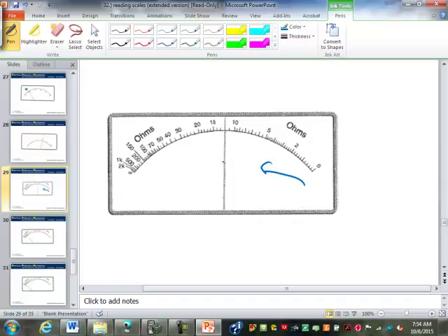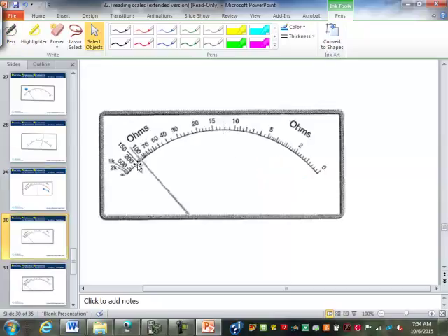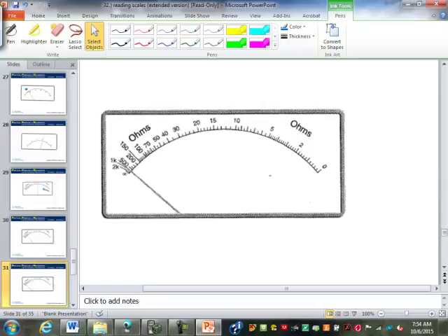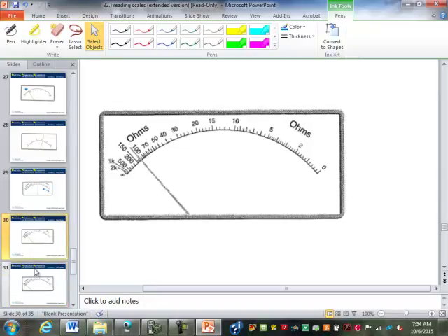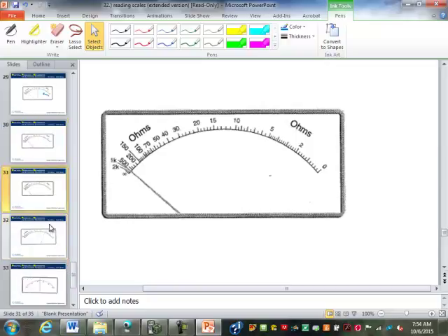So this is actually just 12 ohms is what that's reading. Whereas something like this is reading, well, that's 100 and that's 150. So this is like 125 ohms, 120 ohms actually is what that's reading. Well, yeah, you got to really get in there and see, especially since this has been copied and pasted and then it's up on the projector, it's a little fuzzy for you guys, I'm sure. Like that one there is actually right on the 1000 ohms. Kind of weird that that's 120 and that jumps all the way to 1000. What would you measure? That's resistance in an electrical circuit.